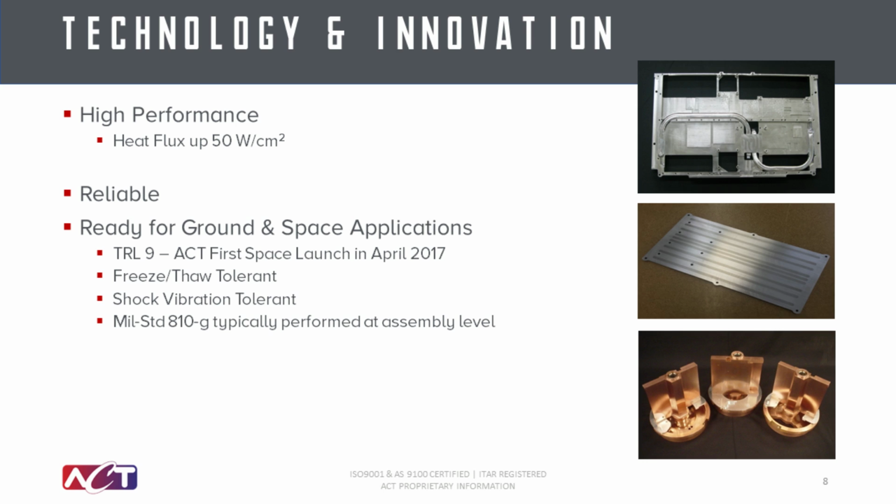The way we do this is the wick structure on the interior of the heat pipe that we talked about previously needs to be able to soak up all the working fluid on the inside of the heat pipe. Overcharging a heat pipe with too much working fluid is a good way to ensure that when it freezes, you'll have fluid bridging the gap across the heat pipe, causing it to bulge when you do freeze.